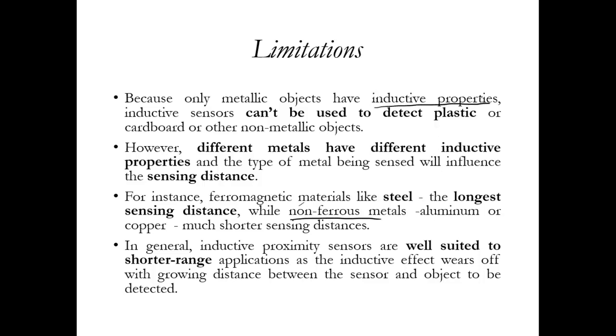That is very important. Sometimes even if we have plastic objects, what we could do is add some metallic objects at their ends, and those metallic objects can be used to sense the distance, and then the rest of the movement of the plastic object can also be tracked. But that is additionally making it cumbersome, though it can be taken as a solution if we have to use inductive sensors only.